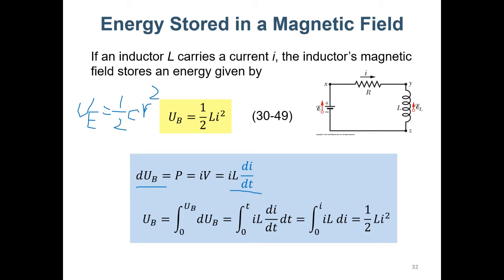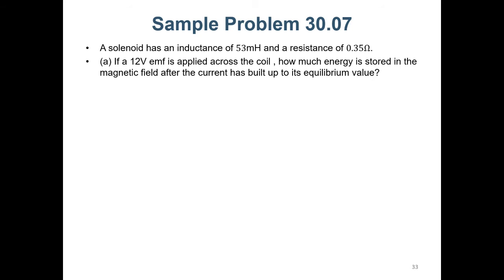So actually it's nothing but integrating I L dI, which is a first order polynomial. So it becomes 1/2 I squared. Maybe we should put a prime here, so that this one and this dummy variable do not repeat each other. So finally, it comes out as 1/2 Li squared. But actually, we seldom use that one.